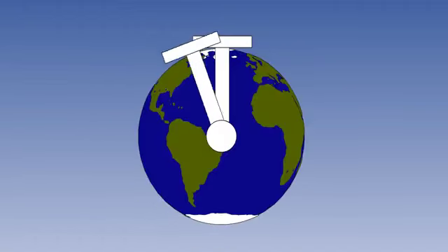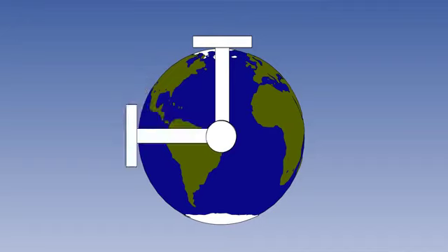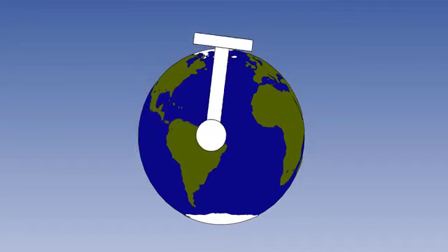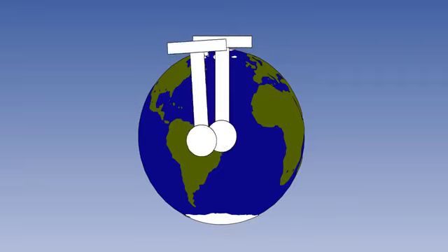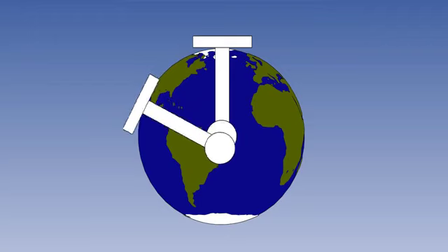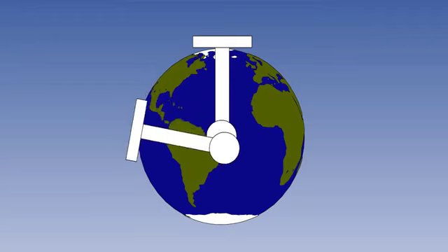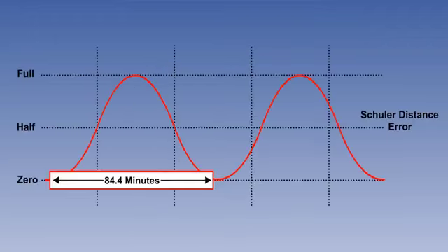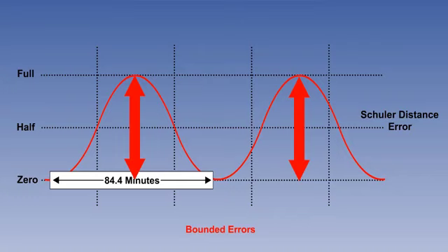We reminded ourselves of the pendulum analogy for normal platform stabilization, and then extended it to include the platform not being level at the start. The Schuler period is always 84.4 minutes, and the maximum displacement at the successive 42.2 minute points is always the same.